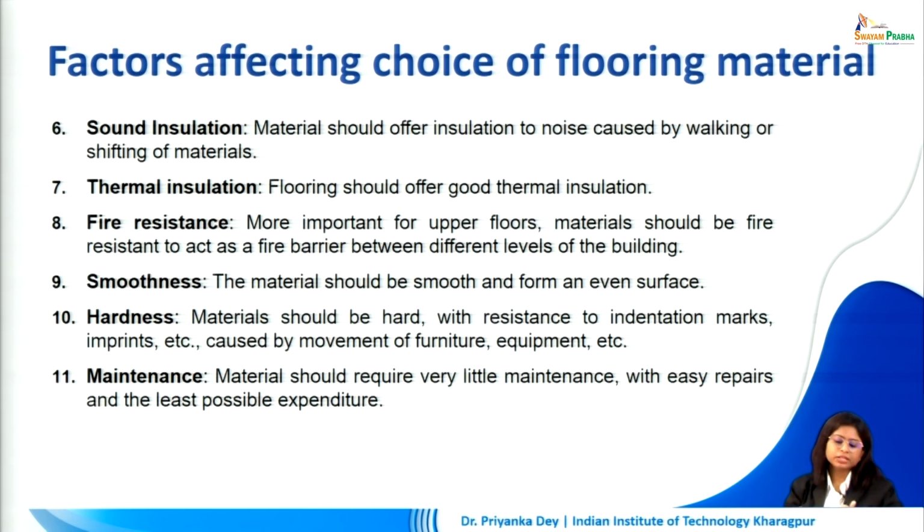The material most definitely has to be hard, so that we can easily move furniture or equipment on top of it. It shouldn't be the case that indentation marks or imprints easily form on the flooring material if we move furniture and anything heavy. Now, especially if you are dealing with industrial buildings where the flooring is expected to receive a lot of heavy equipment or vibrations, the flooring material will have to be selected accordingly. In some cases, some special flooring materials will have to be selected if you are dealing with structures which receive a lot of vibrations, not necessarily just factories.